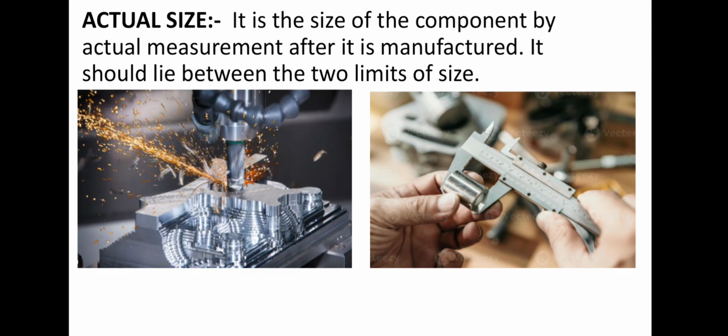Here the actual size. What is the actual size? The component's size by actual measurement after it's manufactured. After the manufacturing, the measured value should lie within the limit. If I am telling 18 plus or minus 0.5, the value should be between 18.5 and 17.5.